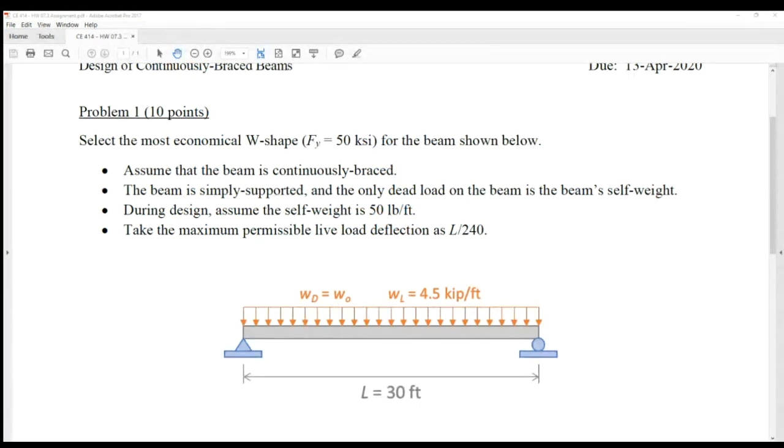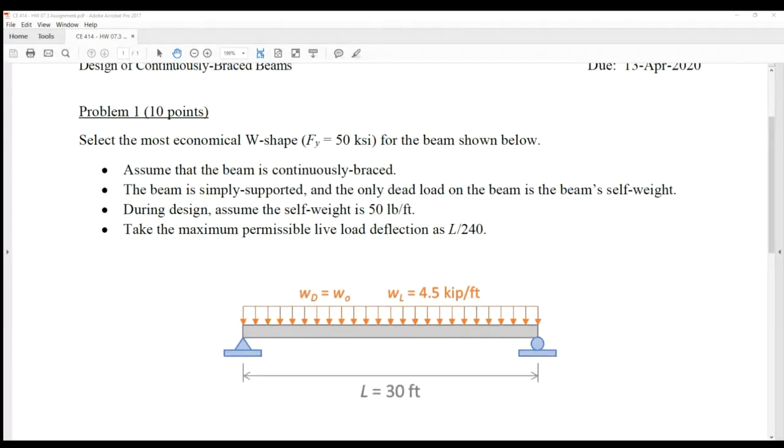That can become a situation in bridge design, but the loads that we're dealing with are far higher in bridges. The reason for the assumed self weight is really to make sure that you don't have to iterate too much on the lighter side of beams, not the heavier side. So to answer your question, yes, there's a possibility, but it's very, very remote in our real life scenarios.